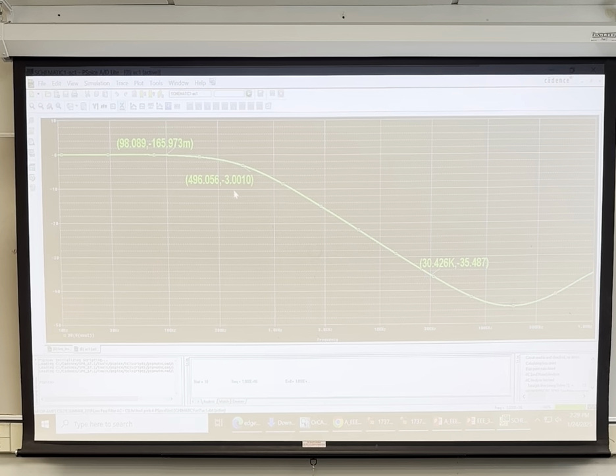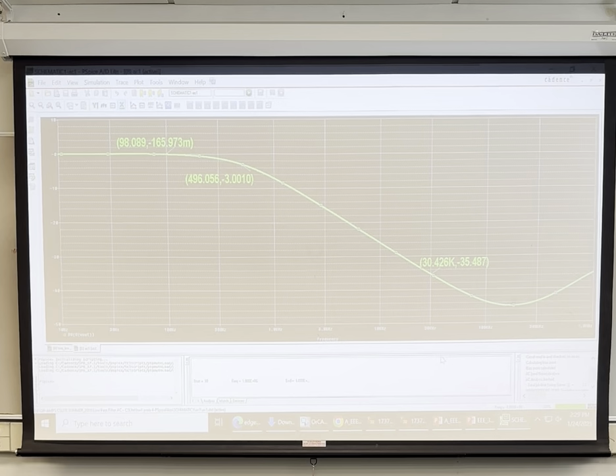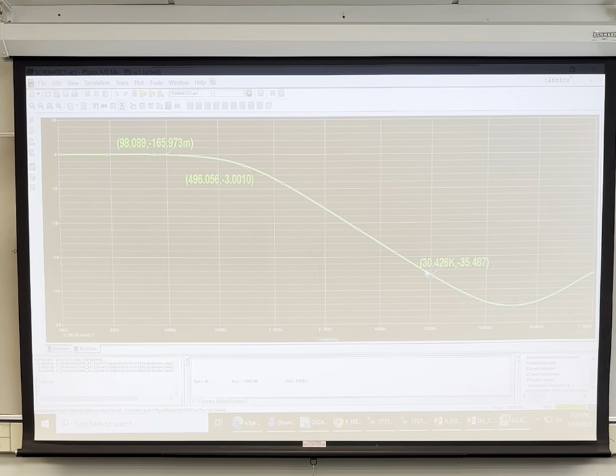So depending on the last digits of the Z number, you'll be ready to guesstimate a cutoff frequency. It's important to have that gap. If the cutoff is too close to your desired, you're going to reduce your desired signal. If it's too far away from the interferer, then the interferer will move back up and be present in the system.